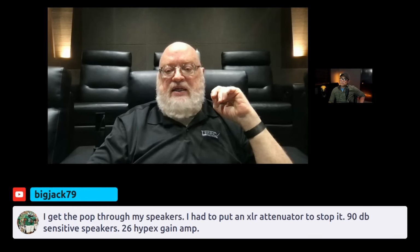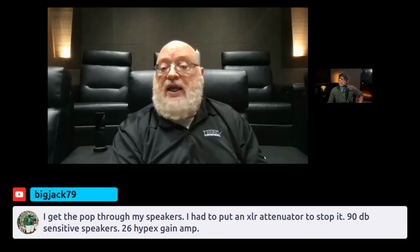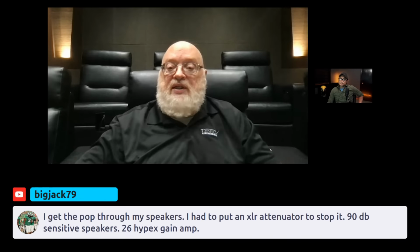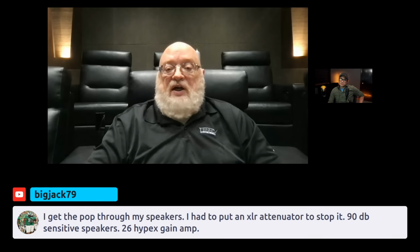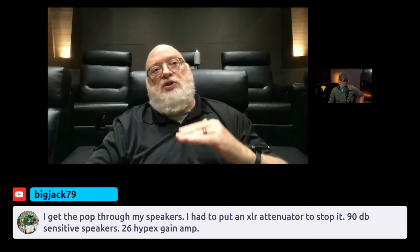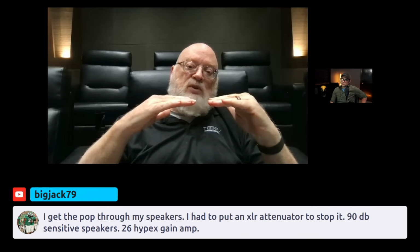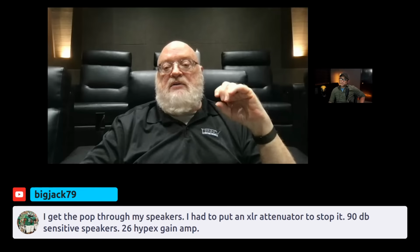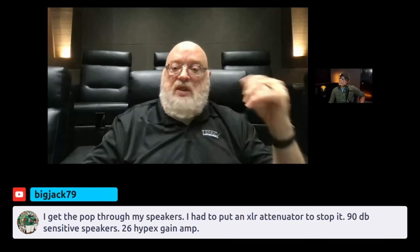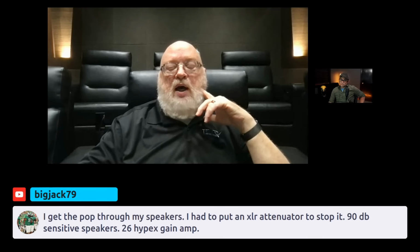But 26 dB of gain is way more than we need. There may be preamps out there that need that much gain because they have a much lower output capability themselves. But the Trinnov is, what, 19.6 or something? Well, it depends on the amplifier. It's relative to what the Altitude can give us. How much more voltage gain do we need to get to the point where the amplifier is at maximum power? It depends on the power rating and what the input sensitivity needs to be based on what the preamp can do.